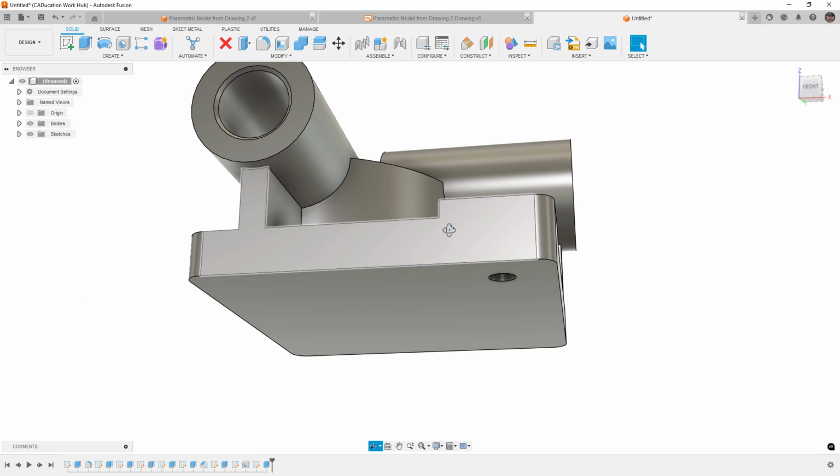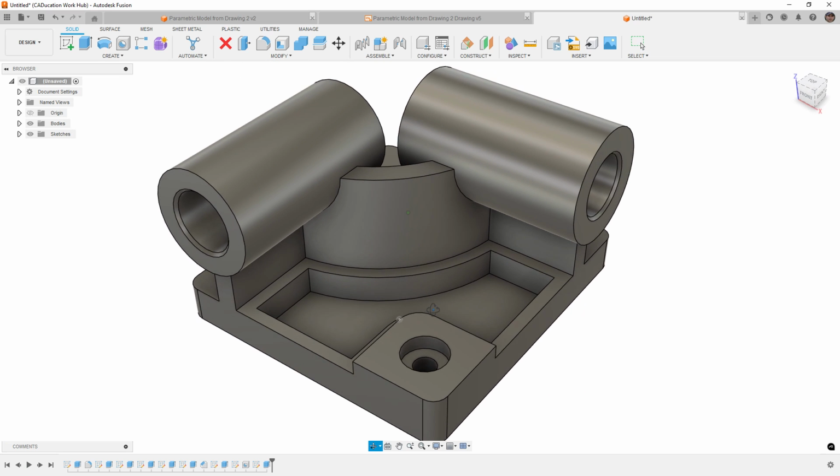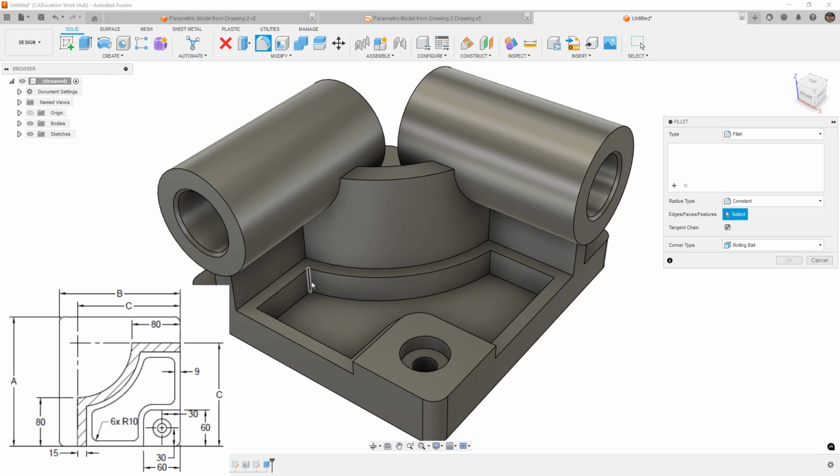Once again, it's important that when we're dimensioning a part like this, if we're using a detailed drawing, that we try to dimension it based on the detailed drawing. So instead of saying go down 20 millimeters, leaving 5 at the base, we can extrude it all the way to the base, leaving a 5 millimeter thickness on the bottom. And again, the reason for this is if we happen to change any of these dimensions, we know that it'll update properly based on the detailed drawing.